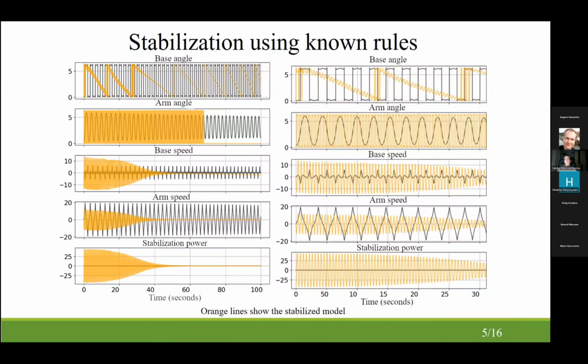On this slide, after finishing the model simulation, I made a module which implements fuzzy control. And using manually found fuzzy rules and output terms, I tested how the system stabilizes the pendulum. It can be seen on the left group of graphs that after some time, the model was able to stabilize itself.